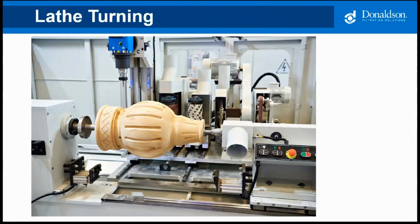Lathe turning is the art of shaping wood into cylindrical shapes, such as chair legs and spindles. One of the fun ones we did involving dust collection on a lathe is at Louisville Slugger, where bats are turned on a lathe. An interesting side note regarding Louisville Slugger is that the bats used to be nearly 100% ash, and they are now mostly all maple. This change in species had an impact on the dust collection system. You get far more curls and strands with the maple than you did with the ash.